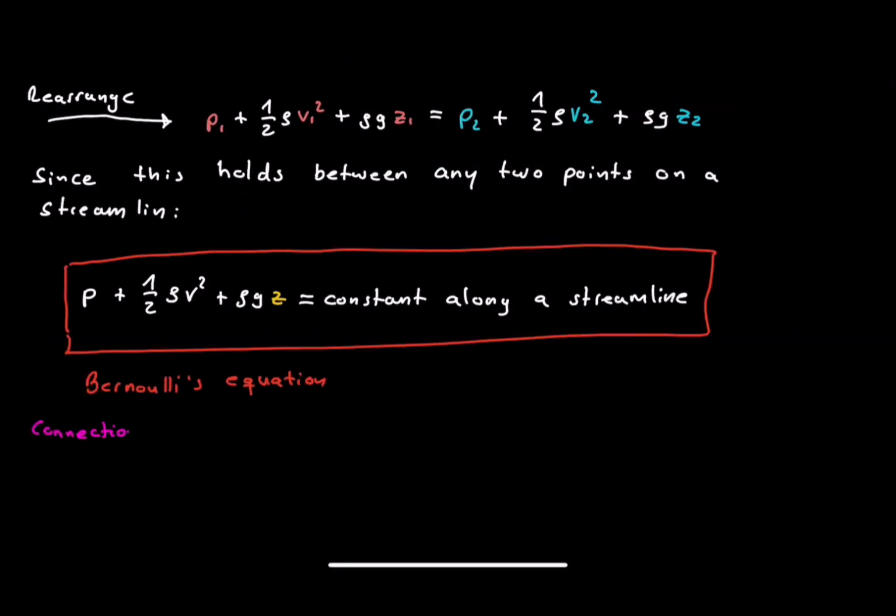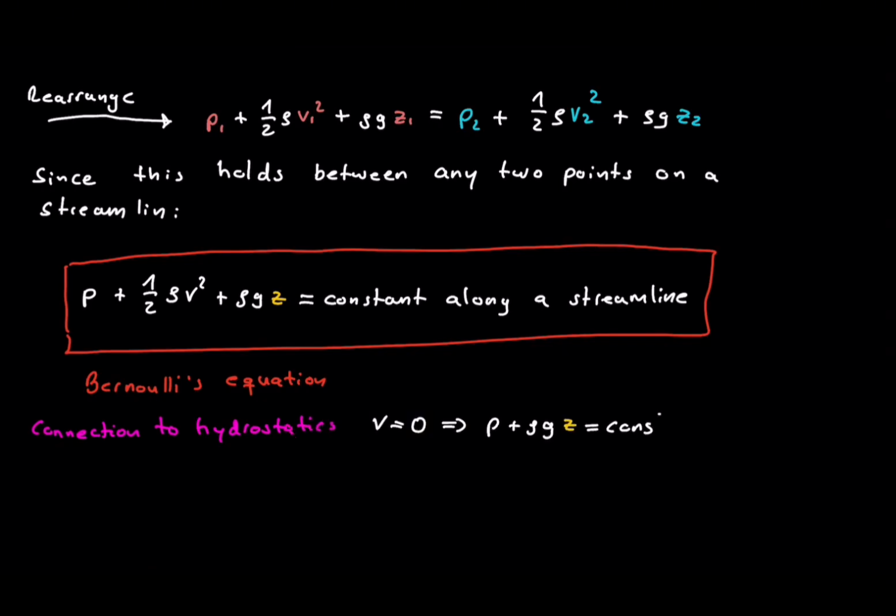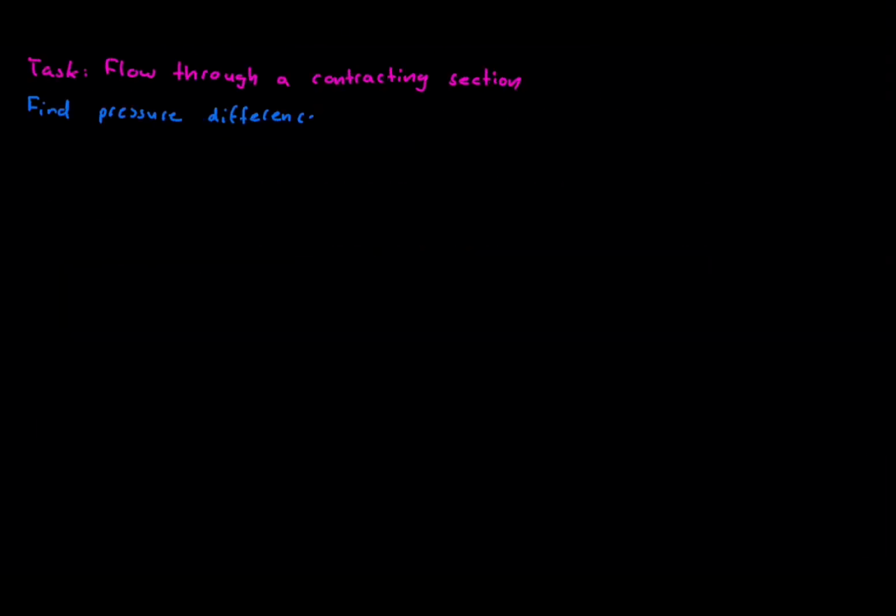That's Bernoulli's equation. The total mechanical energy per unit volume stays constant in steady, inviscid, incompressible flow. Pressure energy, kinetic energy, and potential energy all swap, but the total never changes.